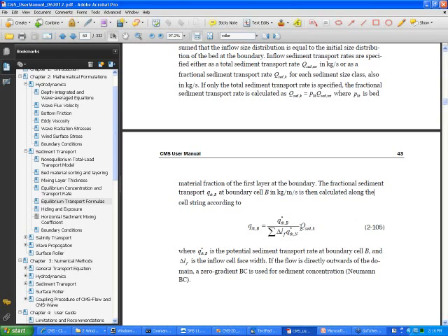For example, your data says that you have so many thousand kilograms of sediment coming in, but your equilibrium formula says it's only 20. Well, all that sediment is going to come into your domain and just fall out, and it's going to create a big mound right at the boundary. And so it tends to cause instability problems. That's why it's not used very much. I've only used these for flume cases where it was measured accurately, and I can apply it with confidence.